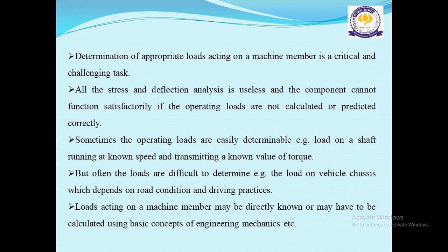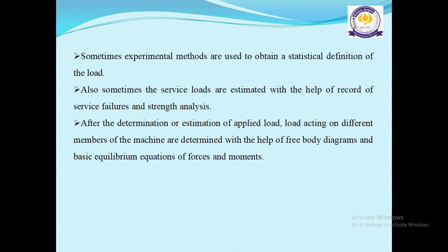Loads acting on a machine member may be directly known or may have to be calculated using basic concepts of engineering mechanics, etc. Sometimes experimental methods are used to obtain a statistical definition of the load. Also, sometimes the service loads are estimated with the help of records of service failures and strength analysis.